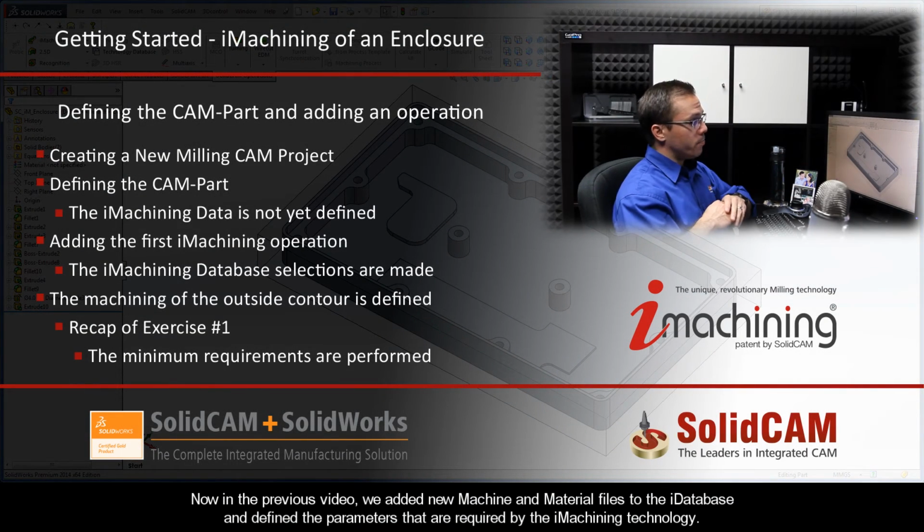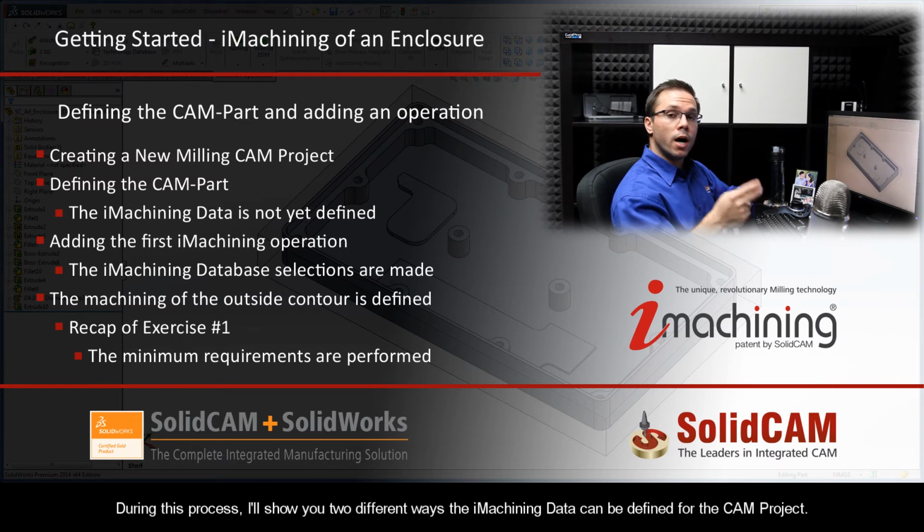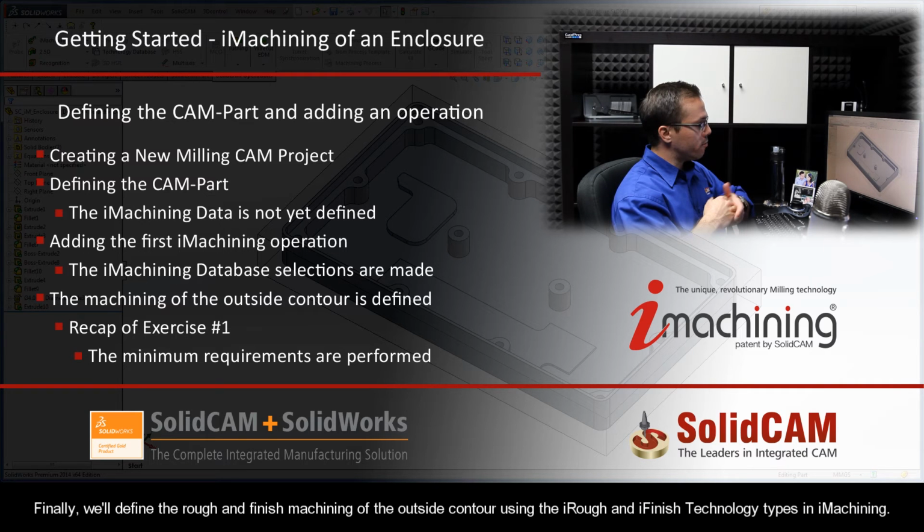Now in the previous video, we added new machine and material files to the iDatabase, and we defined the parameters that are required by the iMachining technology. In this particular video, we're going to do a few things. Just like we've been doing, we'll start a new CAM project and define the CAMPart. Then we'll add the first iMachining operation to start the programming. During this process, I'll show you two different ways that the iMachining data can be defined for the CAM project. And finally, we'll define the rough and finish machining of the outside contour using the iRough and iFinish technology types in iMachining.